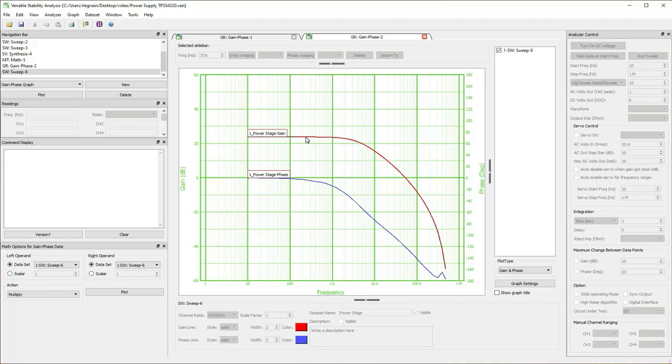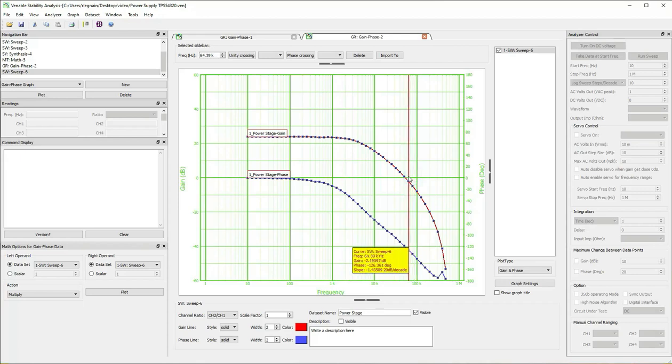The first step is to specify our feedback circuit crossover frequency and phase margin. We will do this by selecting the modulator plot by left-clicking on it and creating a slide bar cursor by clicking on the slide bar button. We shall set the desired crossover frequency by either clicking and dragging the cursor or typing in the frequency. The 0 dB crossover frequency is typically set between 10 to 20% of the converter switching frequency.